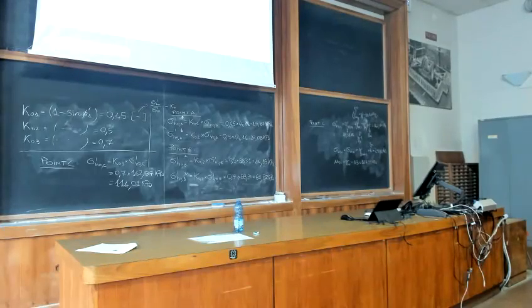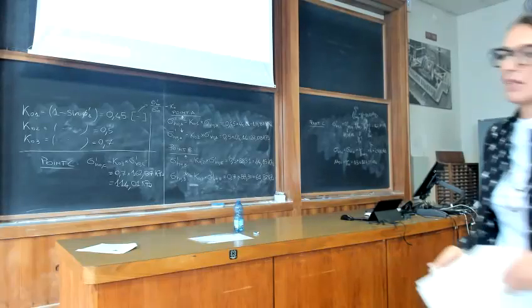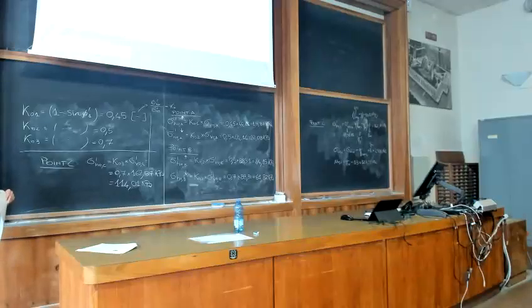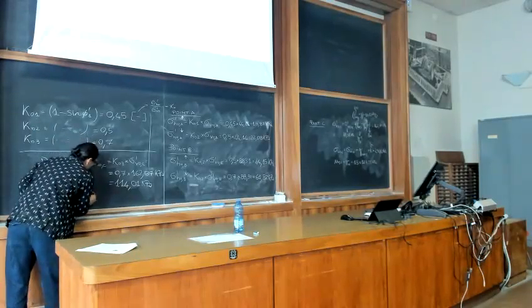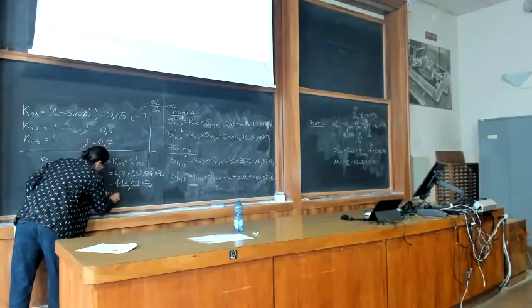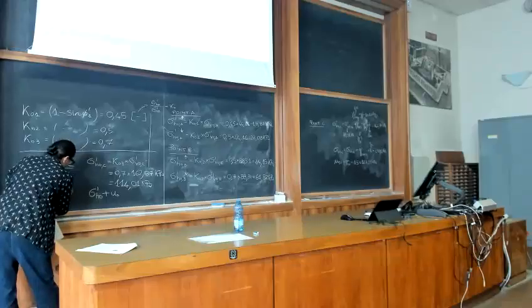If you need to do a calculation in total stresses, because you have fine grain deposits, and then the short term is important, then it could be required to consider also total stresses for horizontal deposits. In this case, what you do, remember what I told you before, is to start from the effective stresses and add pore pressure.